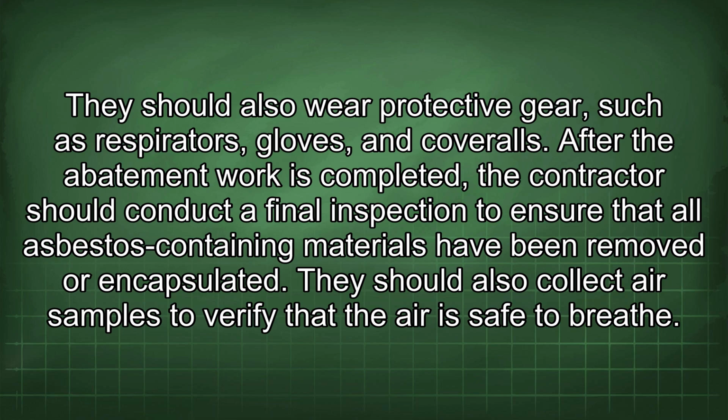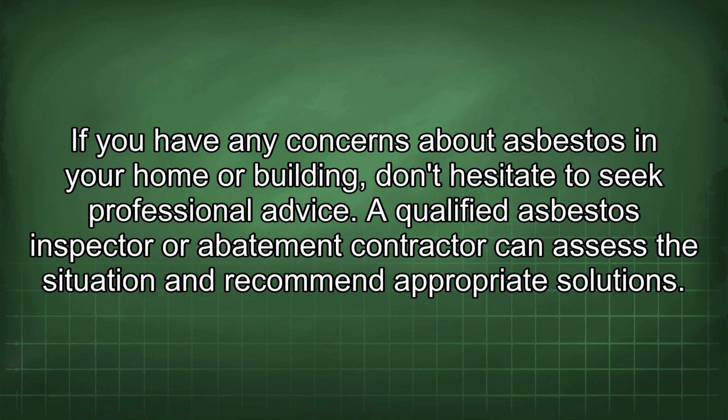After the abatement work is completed, the contractor should conduct a final inspection to ensure that all asbestos-containing materials have been removed or encapsulated. They should also collect air samples to verify that the air is safe to breathe. If you have any concerns about asbestos in your home or building, don't hesitate to seek professional advice. A qualified asbestos inspector or abatement contractor can assess the situation and recommend appropriate solutions.